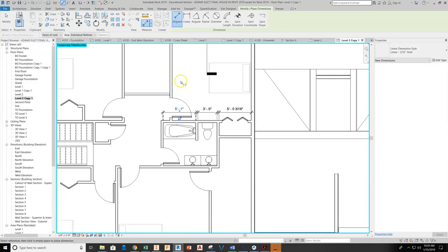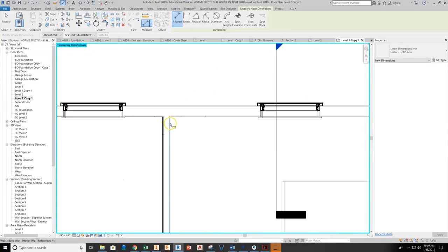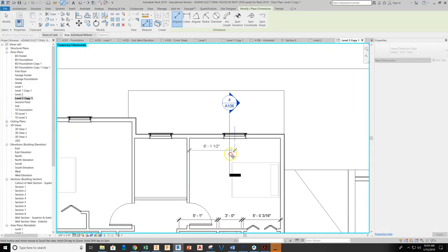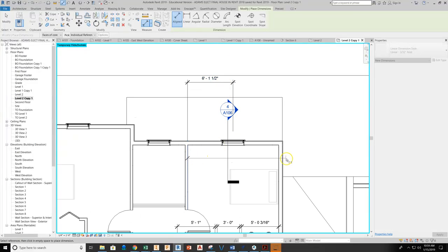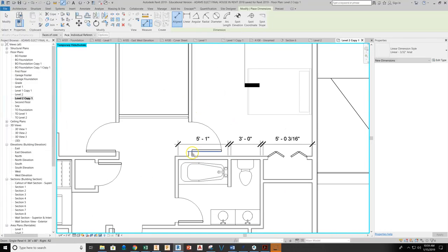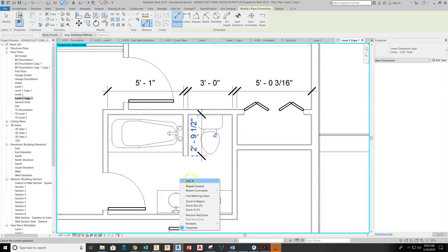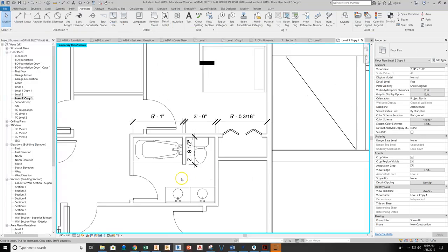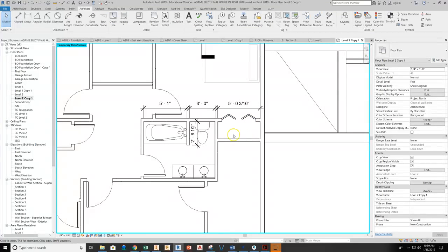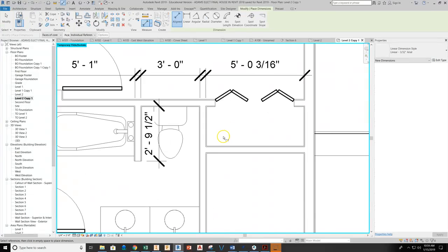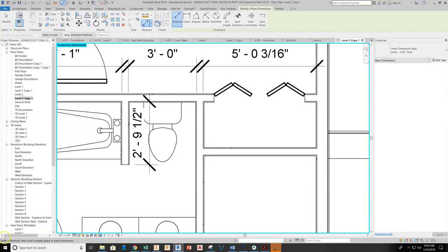This wall for the bedroom would actually get dimensioned here for the outside. We actually go to the window for this, and this would get pulled out, and then we'd end up having an overall for the room size. So it's not necessary to position that in this area, but would be necessary to give this proper information. May or may not be necessary to give the depth of this particular wall, but if you wanted to give that, you can give that in an area such as this to keep it nice and clean and neat. Again, it is as neat and clean as possible to lay out all of your drawings.